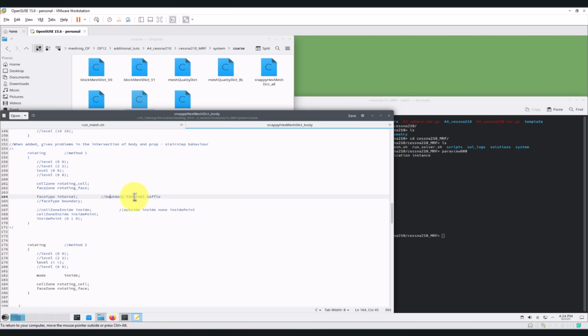But for instance, it can be a case that you want to create a boundary or a buffer. Remember, this boundary or buffer is a zero thickness wall. The difference here, if I recall, is that boundary will let you grow a boundary layer in that buffer. Buffer no, okay? So it is a zero thickness wall, but you cannot grow the boundary layer.